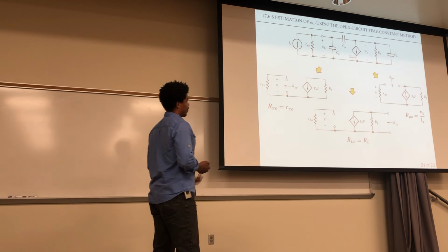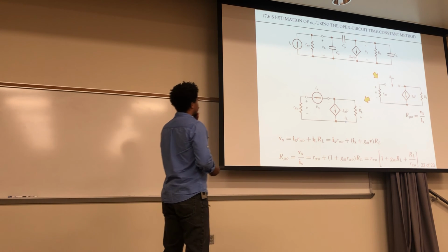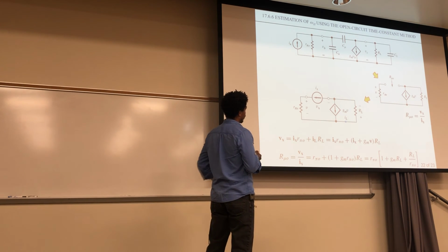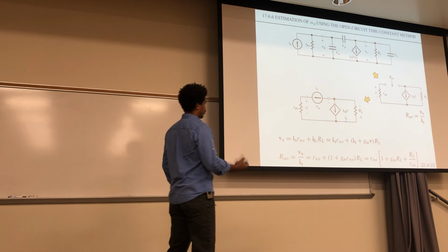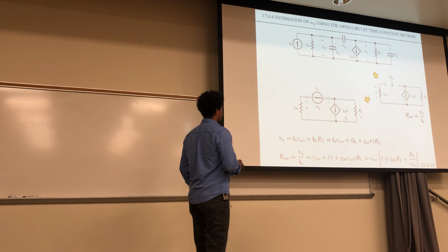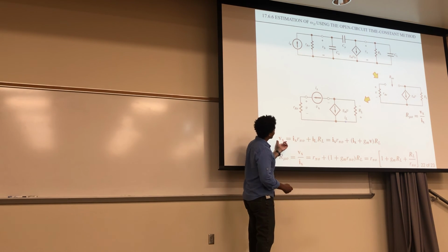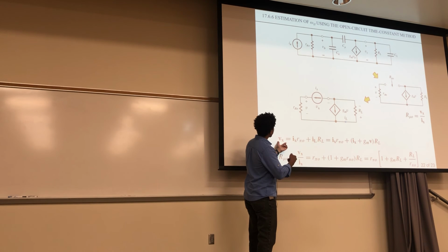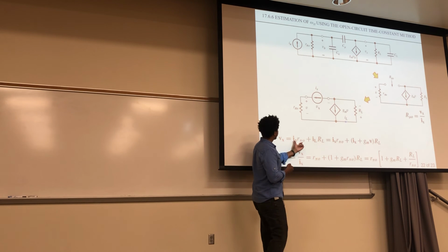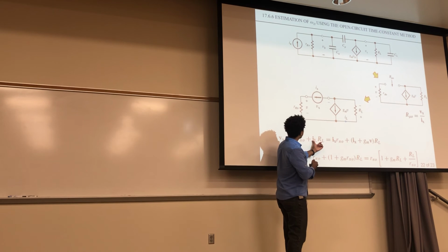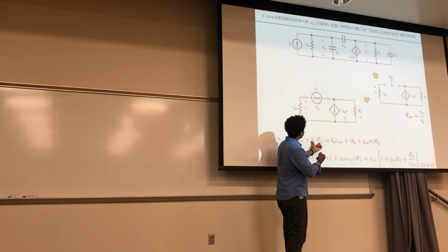So you're going to have to create your Vx. You do that by inserting a current source, this fictitious current source right here, to basically turn everything on to see what the resistance would be. So doing KVL, you can go around this loop. So this Vx right here across that is equal to the drop across here, and also the drop across here.